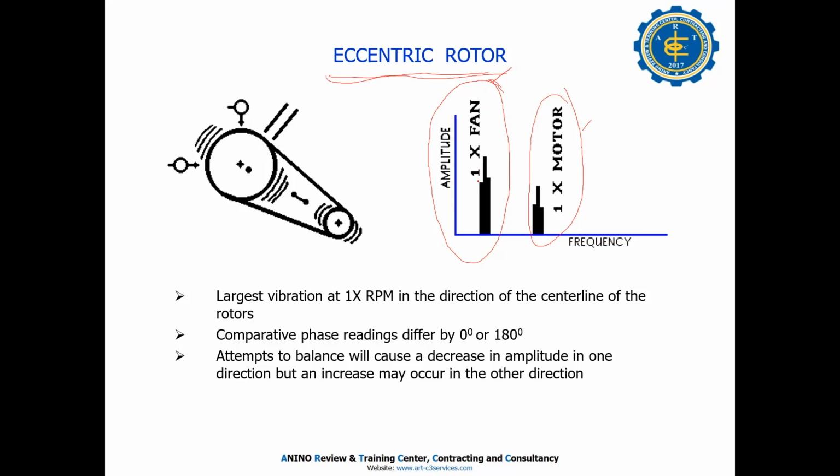You get one small spectrum peak that is the belt frequency. And when your 2x is high, that means there is a misalignment between the pulleys. Yeah, it's good. You have this kind of thing. You can share me the spectrum.